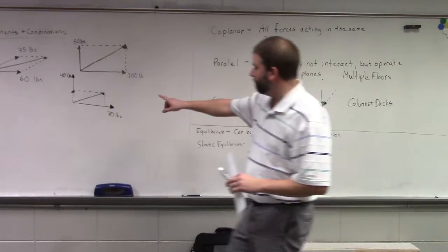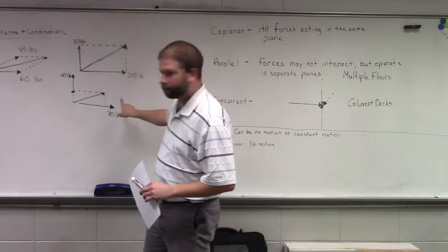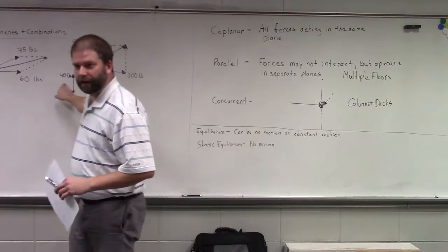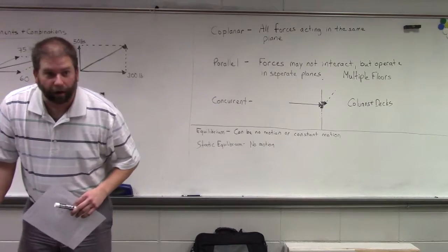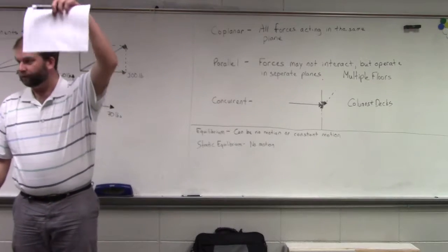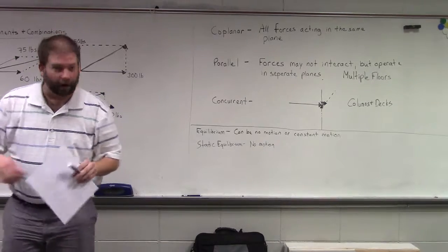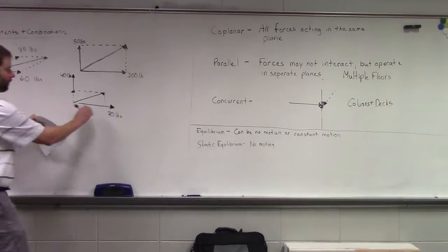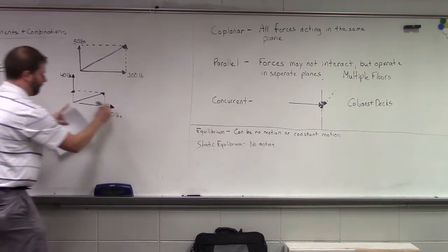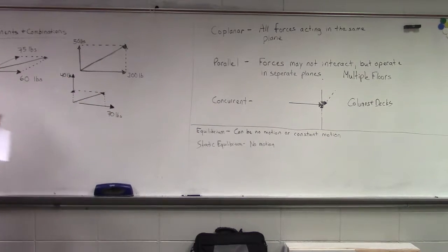Because now I'm moving this force in this direction. But does the deck care if I'm pulling 40 pounds here? No. Or if I stand up on a ladder 4 feet taller and pull with that same 40 pounds? No, as long as I'm not changing my line of action. So we can move these forces along the same line of action. So look at the geometry and figure them out.